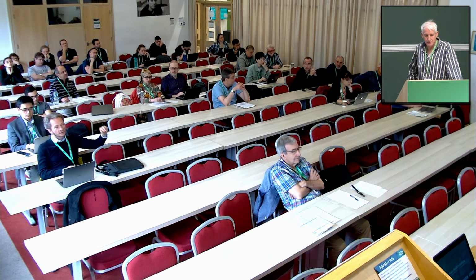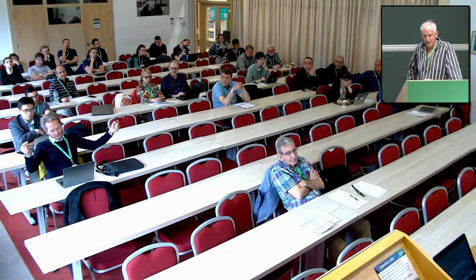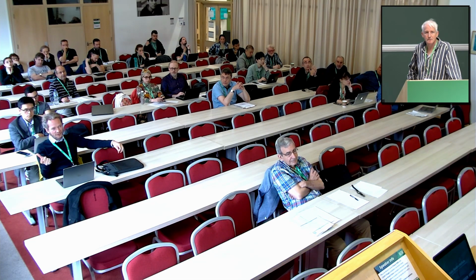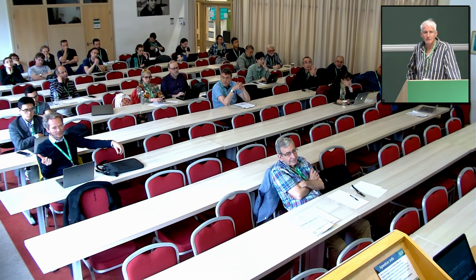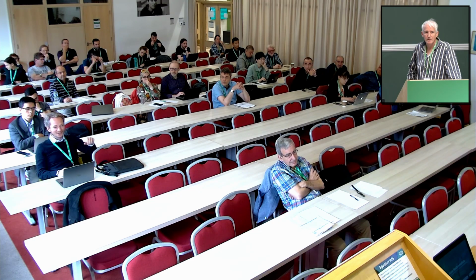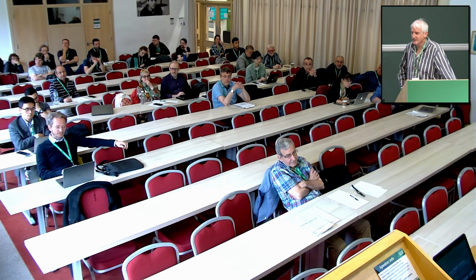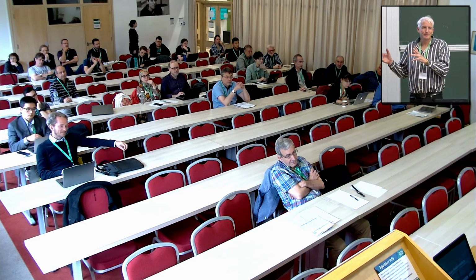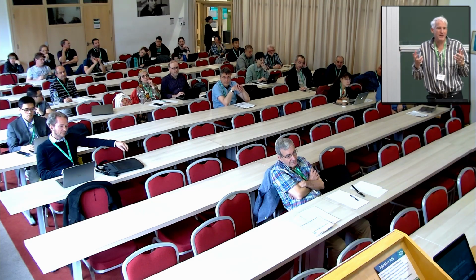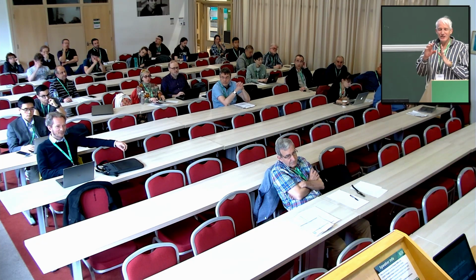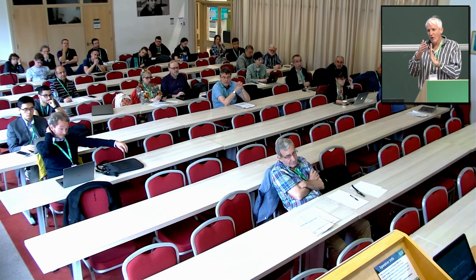Thanks, Malta. Just a quick comment. When you have the reflection, it's basically the same no matter if you've got the piezo effect in there or not, right? But that's probably not surprising because it's reflected off the edge. Yeah, correct. From the edge, it basically looks the same to the wave. So in some senses, you could ignore the effect of the piezoelectric material, solve it as if it wasn't there, and then just add the imaginary part in as it propagates.